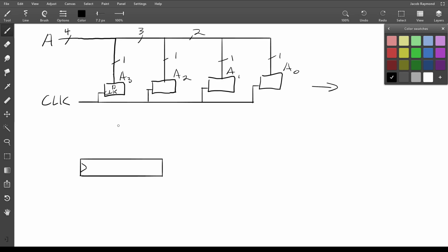But this is just a more generic register where I can have some n-bit number coming in, and then the output, which will also be n-bit, and then just a clock. And what it'll do is it'll take some n-bit number and just store the entire number in that location. And that's what a register essentially is. It's just storing a number. And we can very, very easily create them just by basically attaching the clocks of several D-latches together. Fairly simple. And so this is the first step.